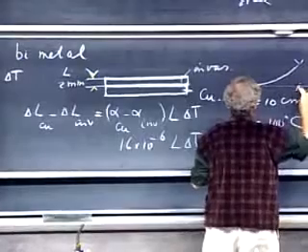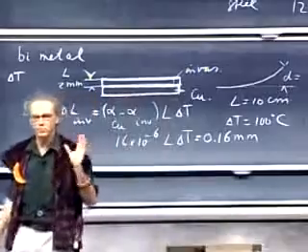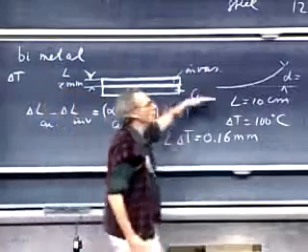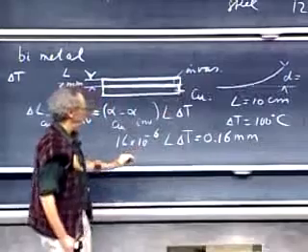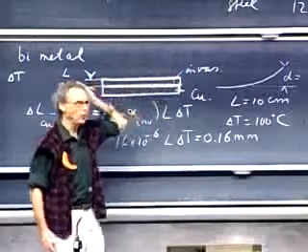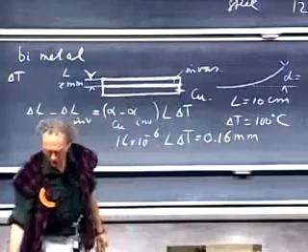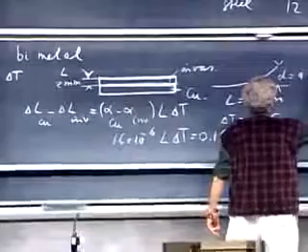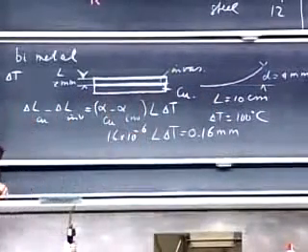substantially. For those of you who are mathematically oriented, I would advise you to make an attempt to calculate that. So you assume that it is a perfect circle. That's a reasonable approximation. And so you have an outer circle, which is longer by 0.16 millimeters than the inner one. And you try to solve and find what that d is. And I went through that exercise, and you want to do that too, perhaps, and I found that it's 4 millimeters, which for these dimensions. 4 millimeters. That's substantial.